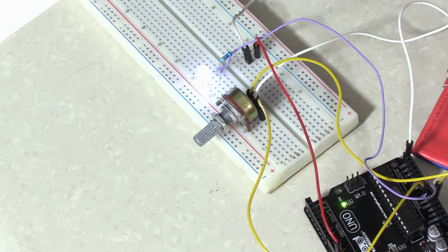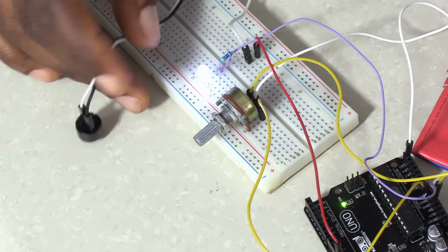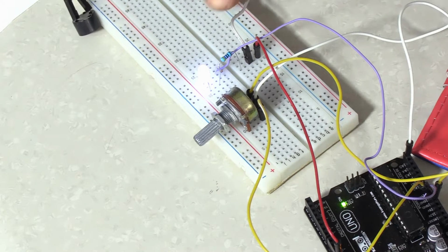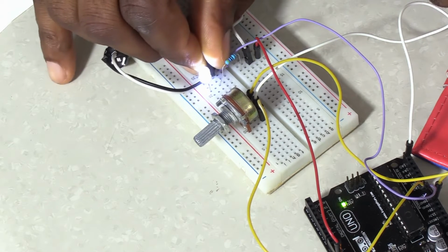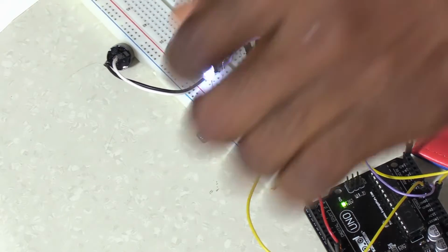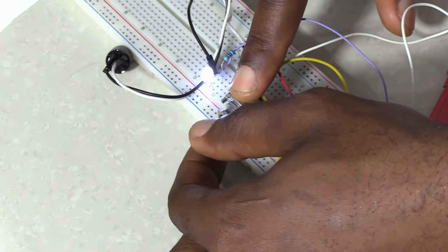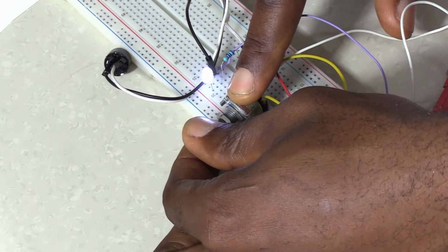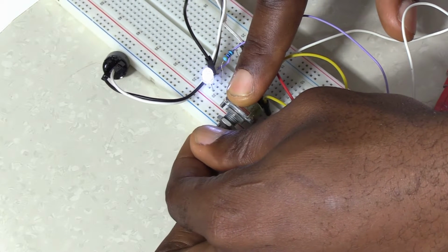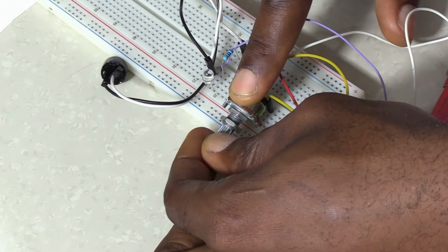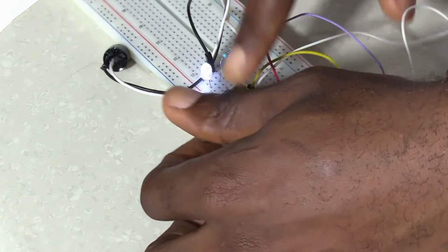Before we go into the programming, I just want to show you the hardware. What you need is a variable resistor, one LED of any color of your choice, and one fixed resistor, which is a 470 ohms resistor, and you can add a buzzer if you like. The buzzer will come to its full sound when the light is at full brightness, and as it goes down, the buzzer sound goes down till you will not hear anything again. So that is the light dimmer for you.